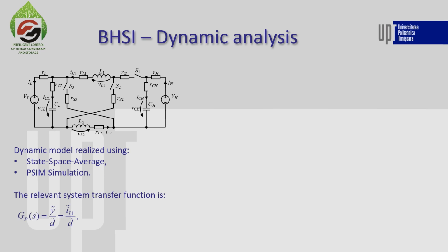Here, because the two inductors are identical, we actually have a simplified equivalent model. It is as simple as the conventional buck-boost converter, just because the two inductors are the same.